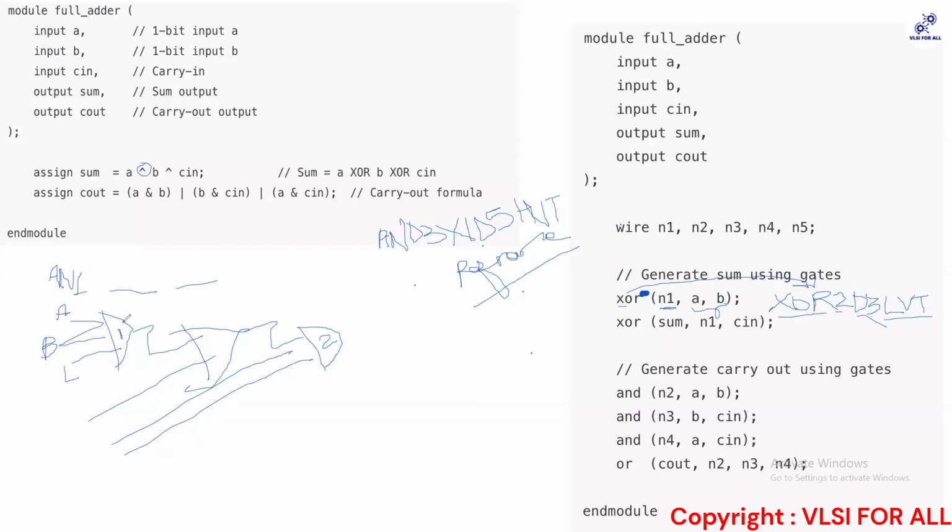But for example, now you have to refer to this. How will you call this? You cannot call it just AND. In my design I have AND3XD. Then how will a person understand whether you're talking about this cell or that cell? So you have to call them through that instance, right? This is the instance in my design, and that's my instance name. But this instance is linked to a cell from the library, which is called a ref name. Understood?